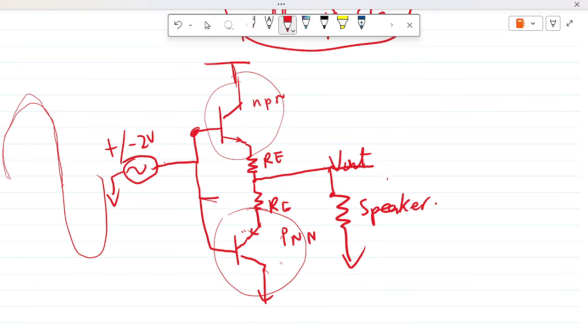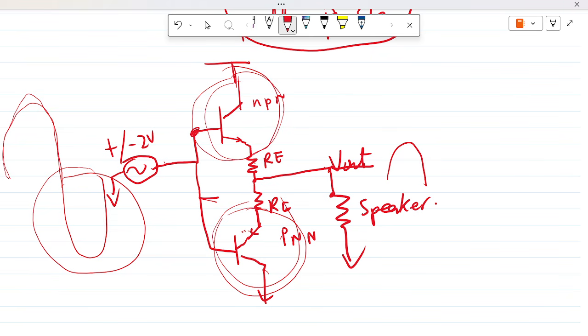So you have an output, and during the lower cycle, the negative cycle, this transistor will not be conducting, and this transistor rather would be conducting. So we will take our time and go much into this push-pull output stage and see how it's better than the emitter degeneration, the emitter follower. It also has its own drawbacks.